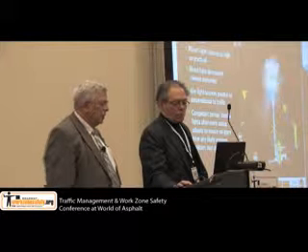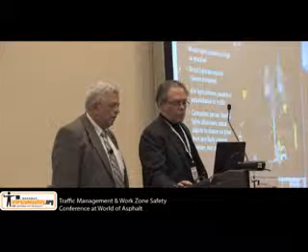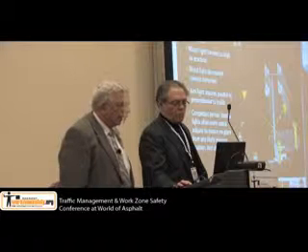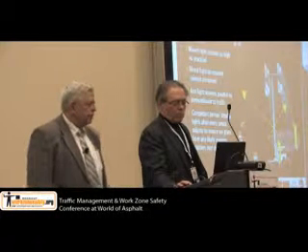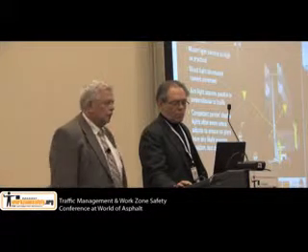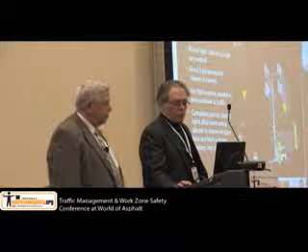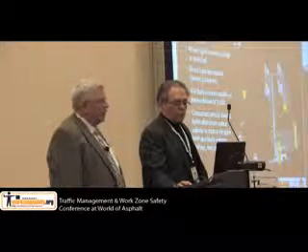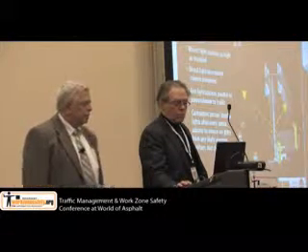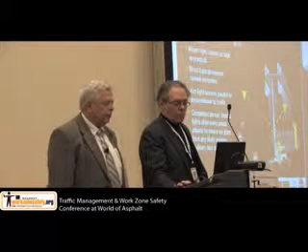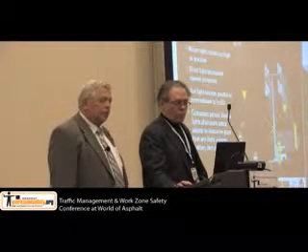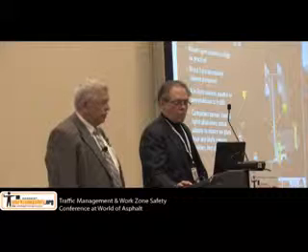Same thing for aiming the light sources parallel or perpendicular to the traffic, so that you're in the right place there. And then obviously the competent person needs to make the adjustments and the recommendation of test driving the work zone so you can actually see what's going on.